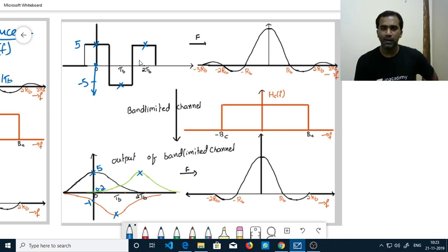So if you transmit through band limited channels, this is how the signal looks when you receive it at the receiver. You are supposed to receive plus 5. Now because of this interference from the second symbol, some minus 1 is coming out. So what is the sample value that you are going to get here? It is going to be plus 4. Instead of 5, we are going to get 4. And along with this 0.2, it will become 4.2. So you are supposed to receive 5, but you are receiving only 4.2 without noise.